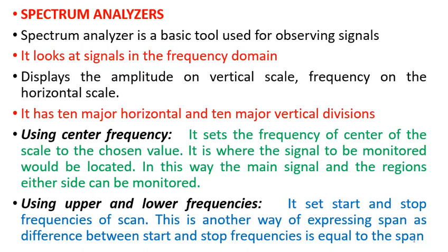That's the fundamental frequency, though we can have harmonics that go higher, and sometimes even frequencies below those fundamental frequencies. So with this approach, we place the signal at the central point of the spectrum analyzer, so that when we start taking measurements it can shoot above that center and fall below that center, depending on the frequency components available in that system.